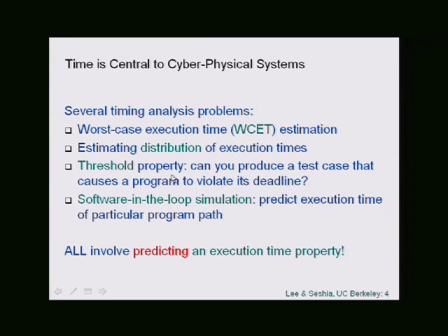And here they're simulating a continuous time model of the continuous part of your system. So typically this could be a Simulink Stateflow model or a LabVIEW simulation or something like that of the continuous part of your system. And then they run the code for the controller alongside in parallel. So they're basically running both the code, let's say the engine control software, and then they simulate the engine itself. And they do this in lockstep.